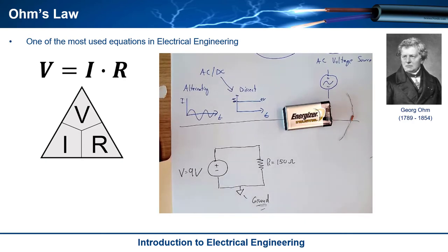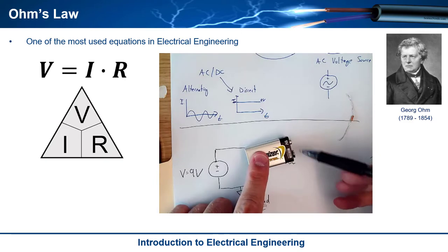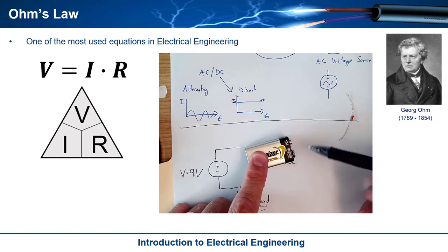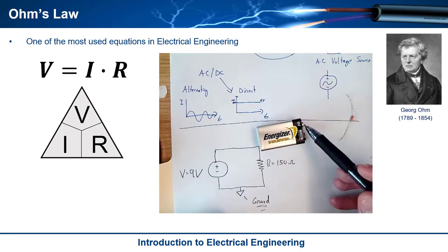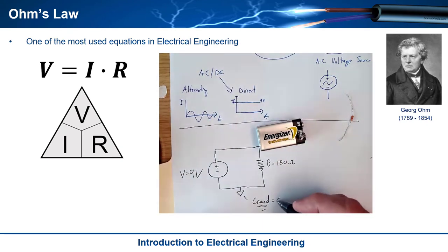We like to use that because when I say I have 9 volts right here, it's 9 volts between this terminal and this terminal. But nobody says what the lowest voltage is at. For example, if this was at 0, this would be at 9. But I could put this at like 15, and this would be at 24. So the 9 volts can kind of float around. What we like to do is lock down the lowest voltage to 0 volts.